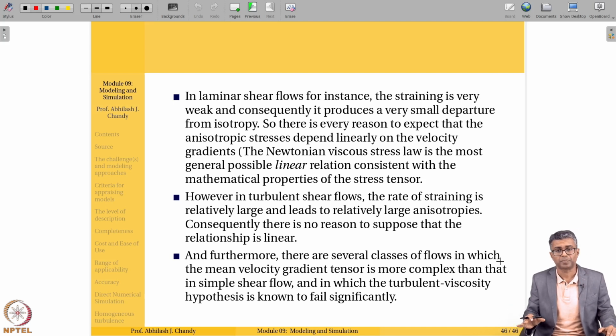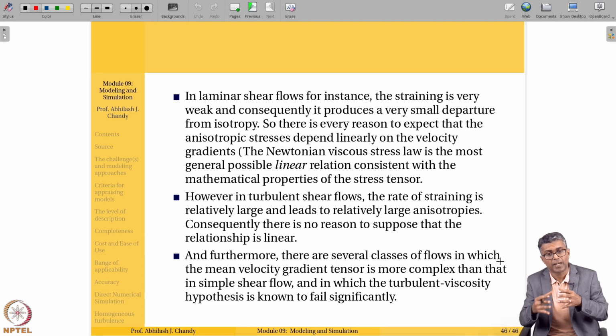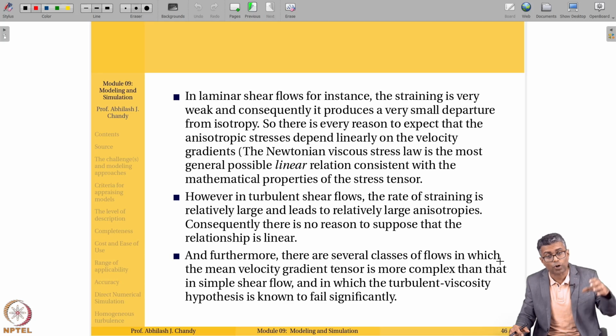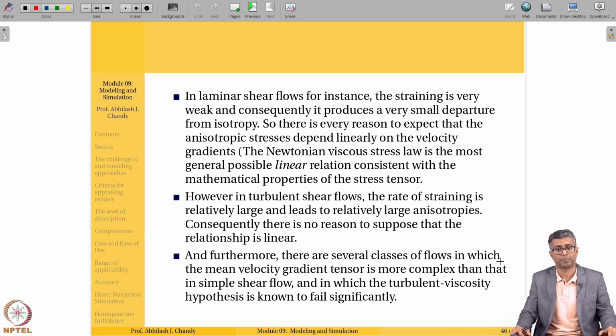That is possible because those timescales are very large, so it does not have as much history. If it was laminar flow through that contraction, having a prior history and causing the mean strain rate to be not zero, that does not happen for laminar flows.